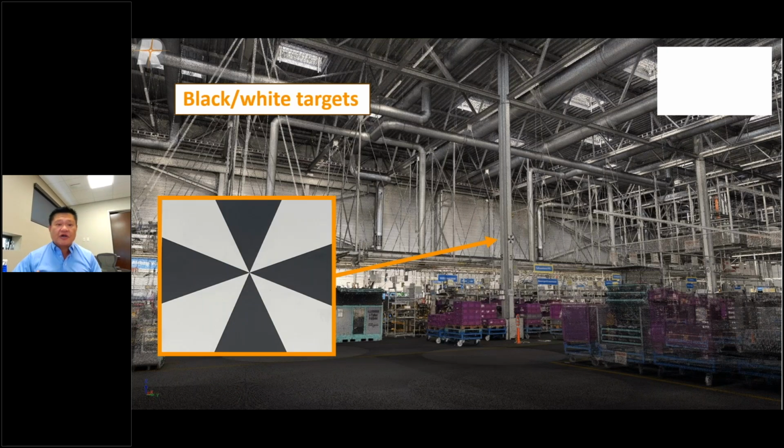In the past, historically, we've always used a highly reflective retro reflector, whether it's flat or cylindrical, no sphere. We've done some testing in the past with spheres, but in order to maintain the high accuracy of the target, because it didn't transfer down to the control, right? Because you use the targets to reference control, and we try to take out as much error as possible. So we've always had great success with the highly retro reflective targets. But now, introducing a black and white checkerboard type target, our scanner can also recognize this as well.